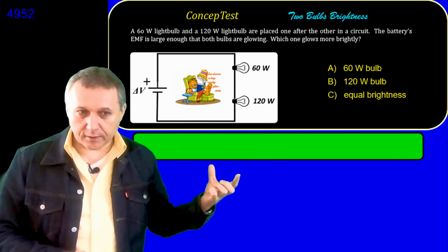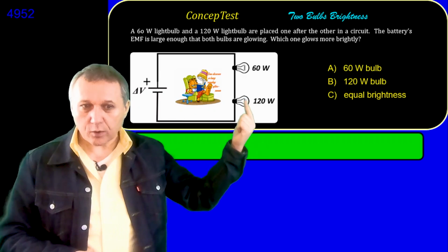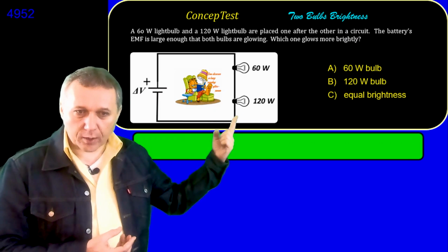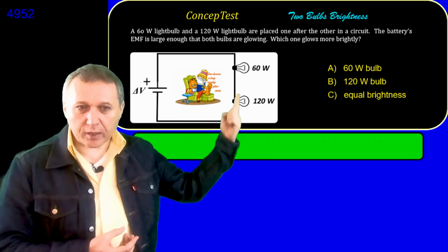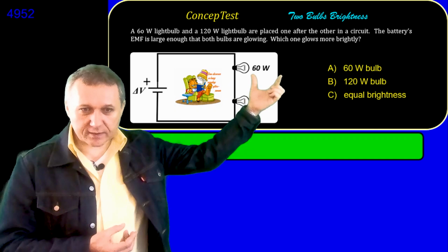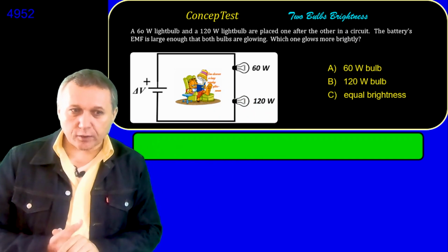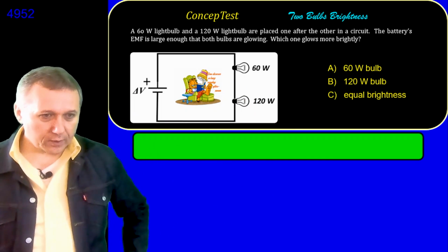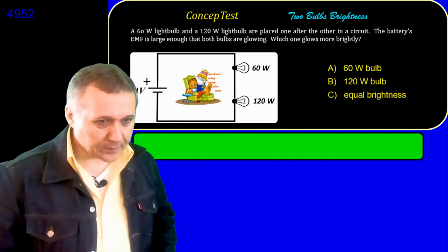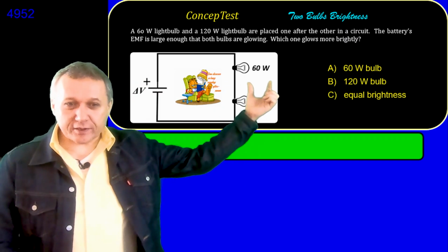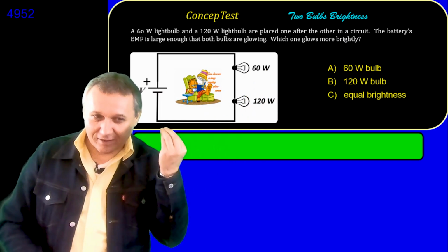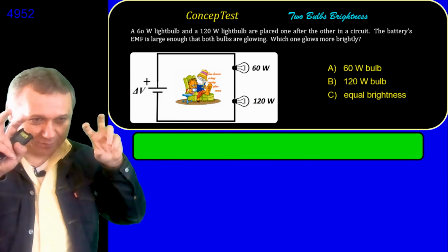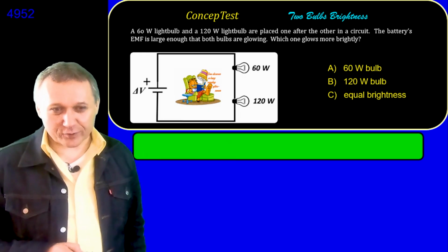So let's find information about the resistances of these bulbs in order to get information about the actual power produced by this bulb and that bulb. Because these 60 watt and 120 volts are not truly intrinsic parameters. Again, they're intrinsic only for the territory of the US, right? But of course, we need to use these numbers in order to get information about that resistance. So we need to use the formula which we just derived, the formula for the power.